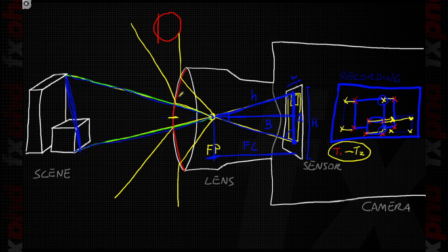So what can we do for this? Well, we can remove the lens distortion. And this is a very delicate part of the camera tracking, because getting a good lens distortion pattern is going to solve way better our triangle. If we get something like a margin of error, our triangle is going to get far from the original point, and this is going to create an error of solving. So we need to calculate, first of all, the distortion of the lens.